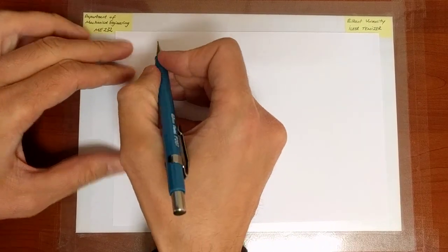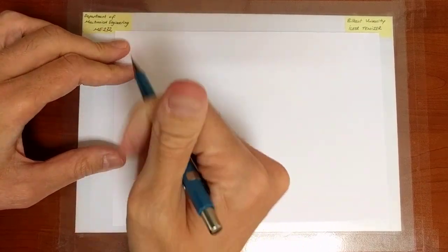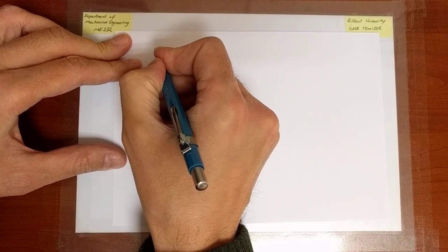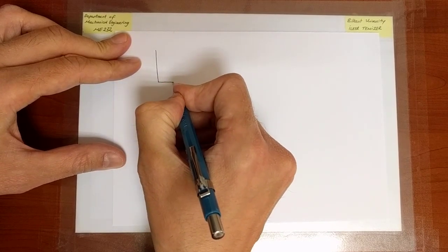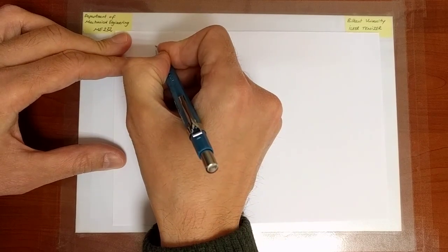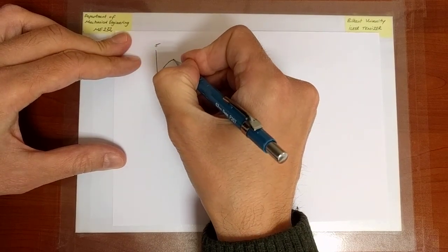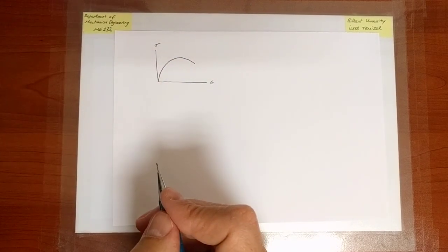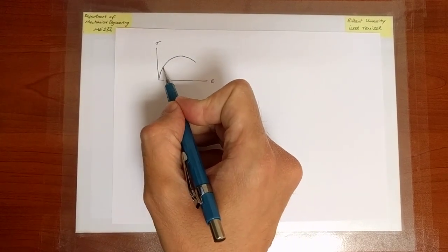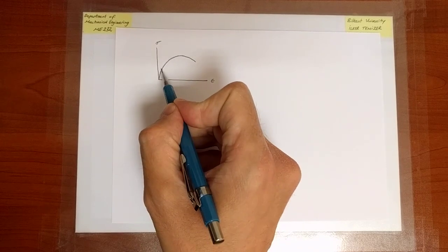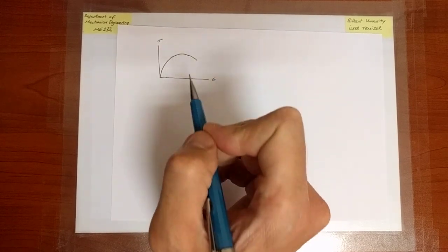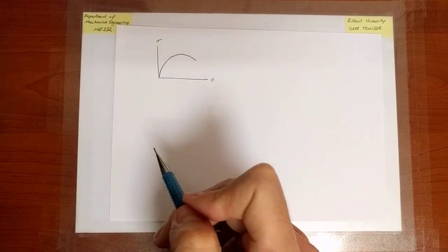Alright, so we're discussing the stress-strain curve, and we are conceptually at this point preferring the idealized stress-strain curve. And our idealized stress-strain curve is something that looks like this. Now, what we've said is that this is a prototypical stress-strain curve, probably has to do with a metal. I have not drawn a distinct yield point, but I could idealize that as well. There's an elastic portion followed by a plastic portion. It's probably a ductile metal.